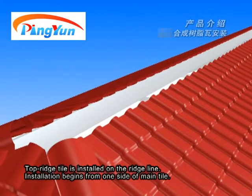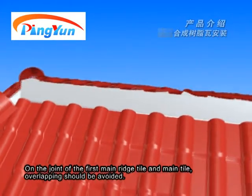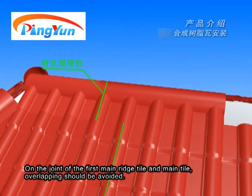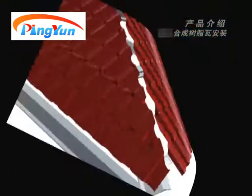Installation of top ridge tile. Top ridge tile is installed on the ridge line. Installation begins from one side of the main tile. On the joint of the first main ridge tile and main tile, overlapping should be avoided, to overlap one wave unit between two top ridge tiles.